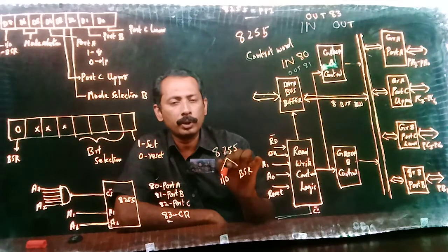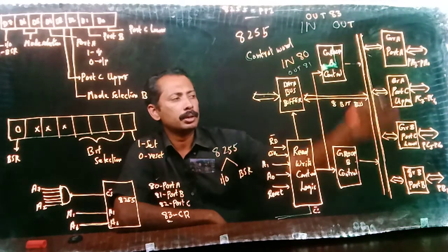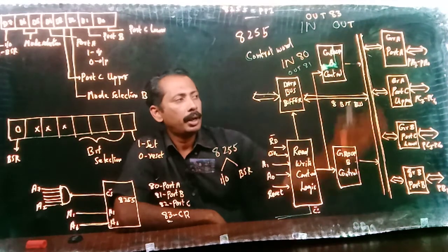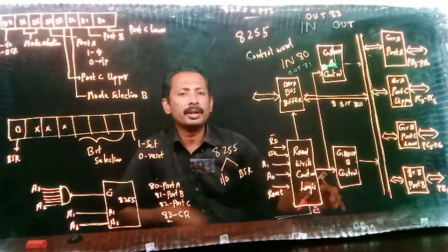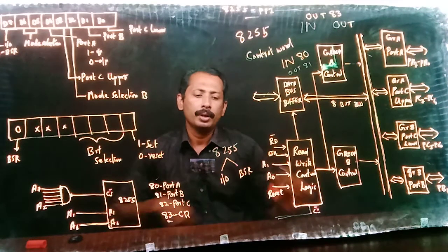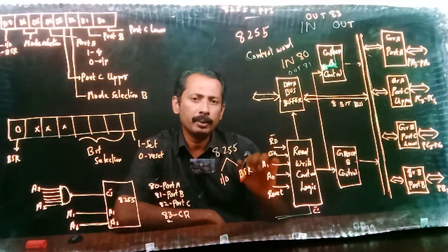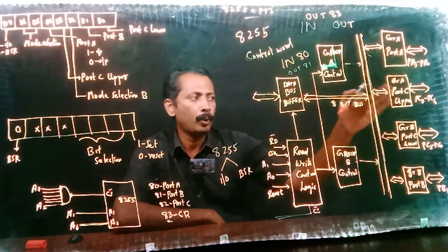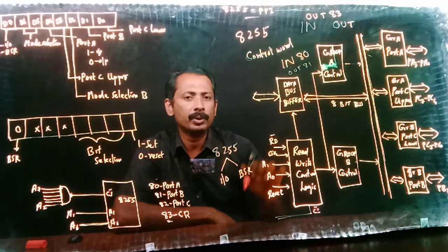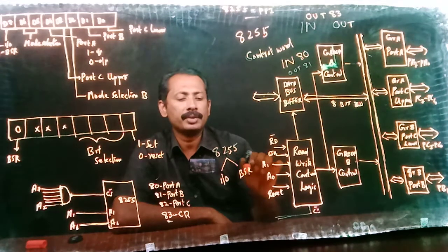In the input output mode, all these ports work and we can configure each port as an input port or output port. In BSR mode, only port C works. In BSR mode only port C works. BSR stands for bit set reset.